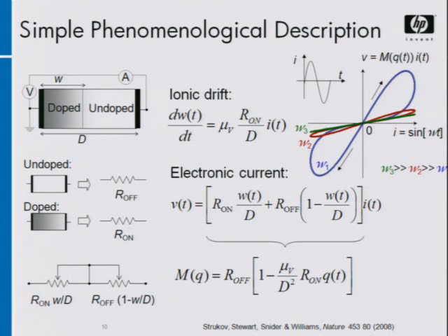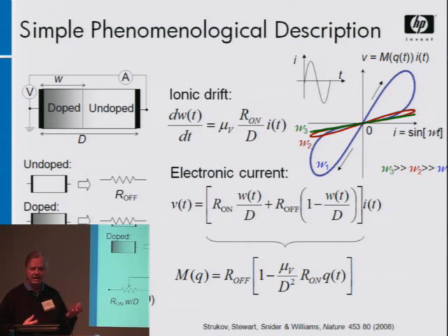And so what's happening? Well, now practically all of our electronic devices are at the nanometer scale. And if you start reading papers about what people are observing in their electronic circuits, what are they seeing? They're seeing all sorts of anomalous capacitance or anomalous inductance. They're seeing all sorts of hysteresis in their circuits that they weren't expecting. And what is it? It's memristance. They've got high voltages, they've got high fields, small distances, the atoms are starting to move. And so memristance is essentially cropping up all over in all of our electronic circuits.